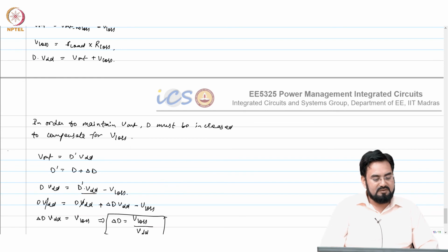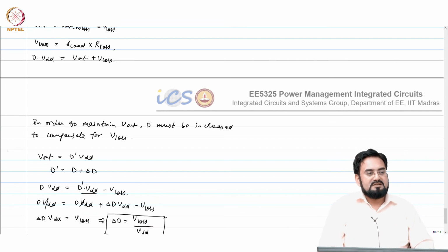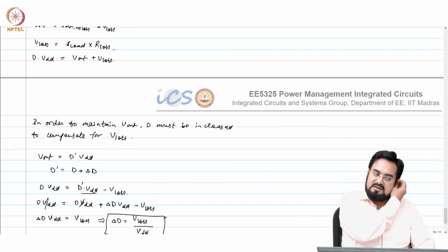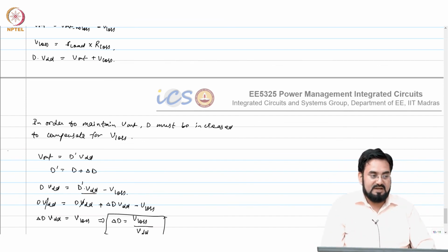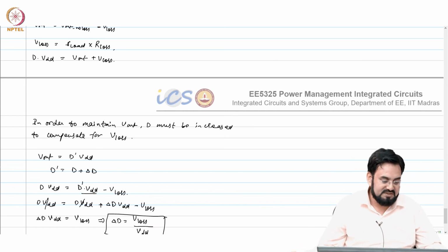So, everything will contribute to your loss in efficiency, and we will also take an example where we will see how it maintains the efficiency across a wide range of V out over V in, compared to an LDO or linear regulator, where if dropout is increasing, or V out by VDD is smaller, then the efficiency drops. We will see how it is able to maintain around 90% or above across all the range. So, we will take 2 or 3 values and calculate the efficiency.